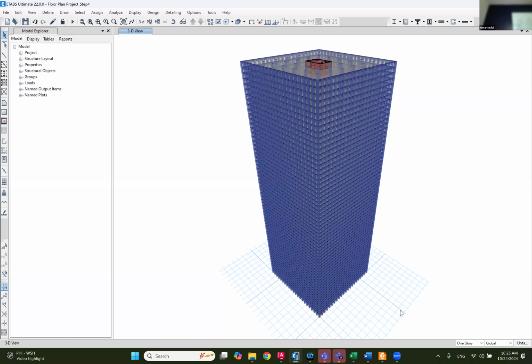Once you have 12 models ready, but before you produce the 12 models, wait until you put in the seismic load, because you don't have to put the seismic load in each model separately. You would waste, I don't know, an hour doing them separately. So once you do this, put in the seismic load and then produce the other models. Then the other models can each be run separately. Like you guys, team 4, everyone is going to run 3 models and get the results. Maybe one team will see the impact of the coupling beam depths, shear wall thickness, spandrel beam depths, and then you come together and put the results together. I believe that's an efficient way to do it. Is that okay? Good.